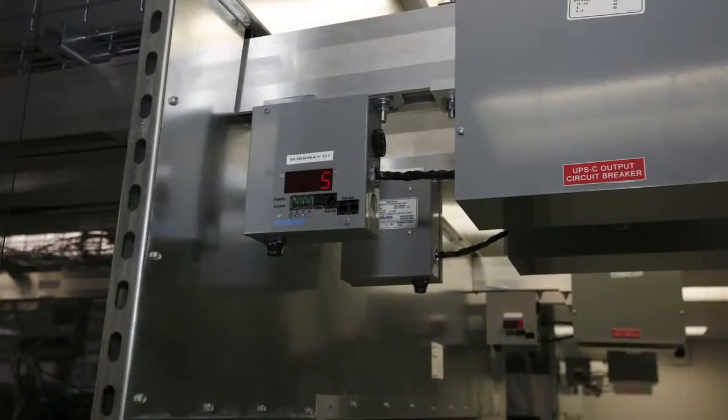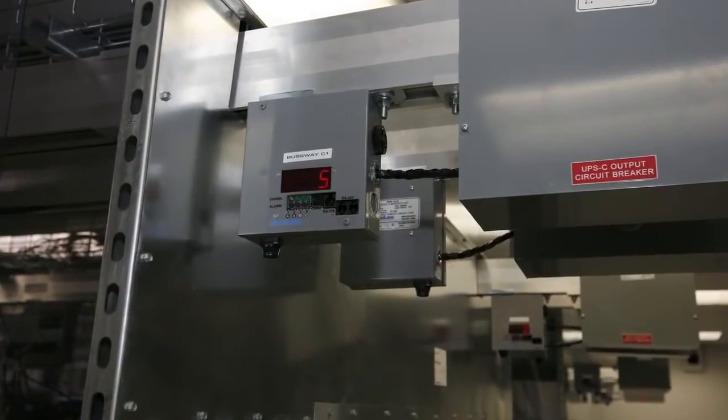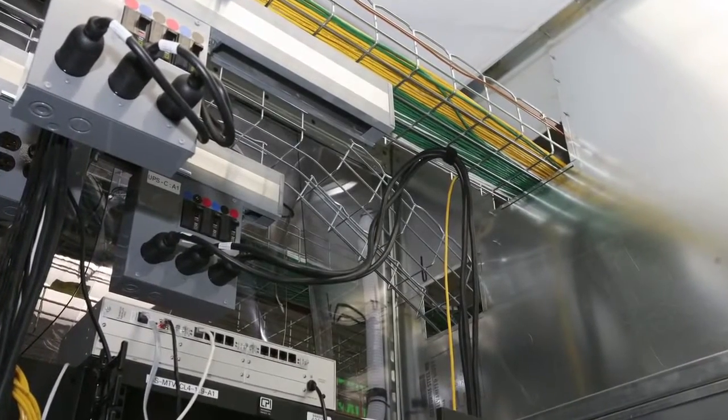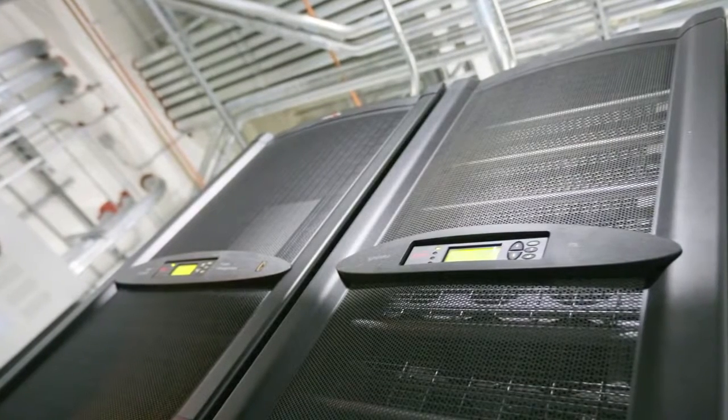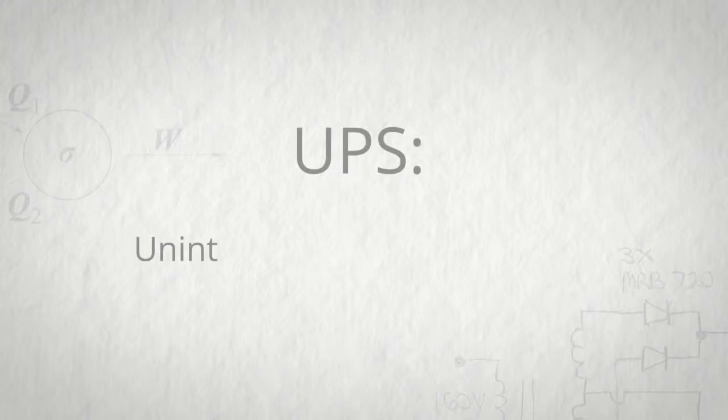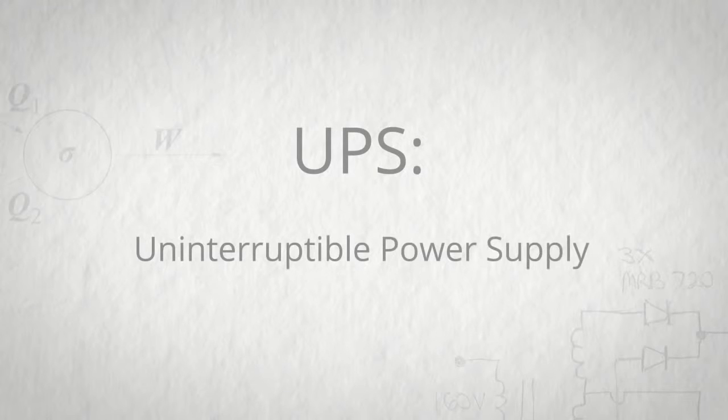In a data center, you pull power in from the electrical grid and you convert it down to the voltages that are needed for all the components in the data center. And there's a lot of conversion stages in there. By minimizing those conversion stages, you can save money and save energy. Also, by making each conversion stage more efficient, you can save energy as well. Traditionally, one of the big losses is the UPS system, the uninterruptible power supply.